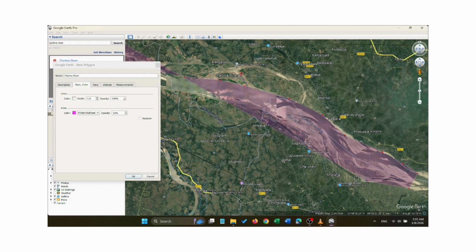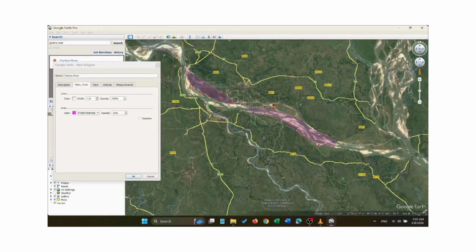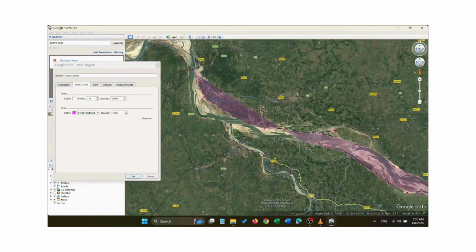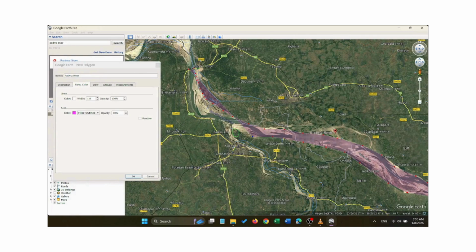Let's say this is our study area, so I backed again, and I have to go back to my initial point to complete this polygon or study area. So this is the shapefile of my study area. From here, press OK.